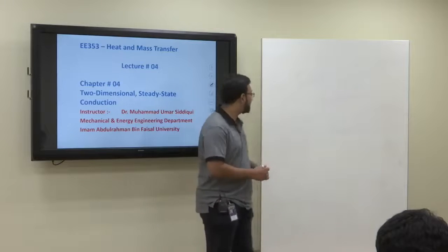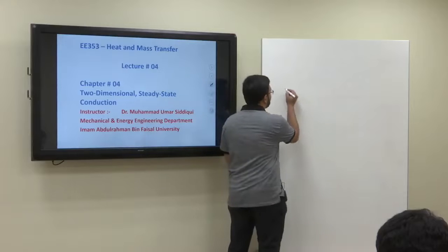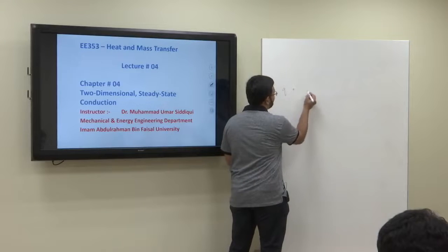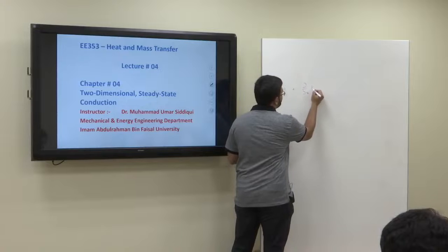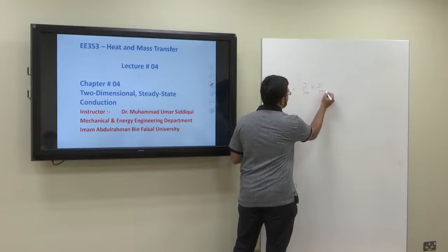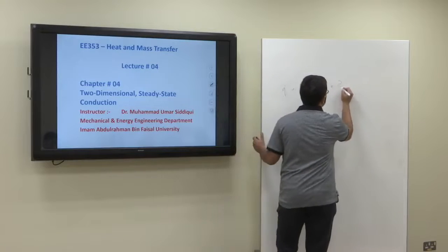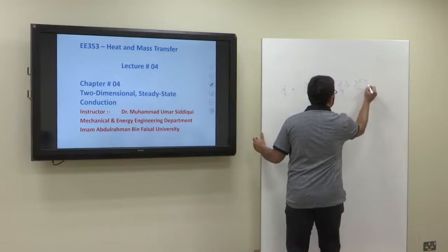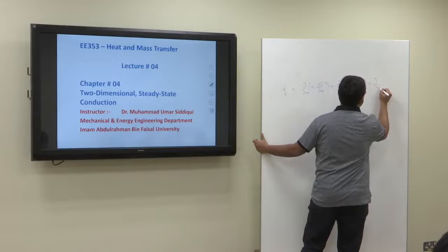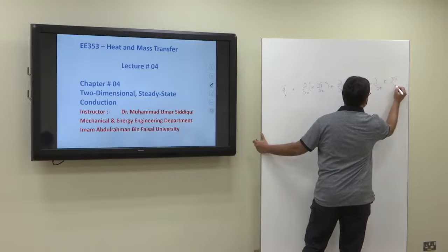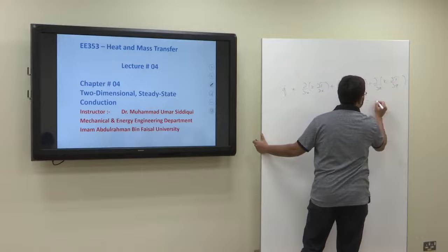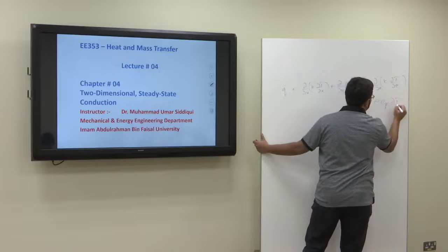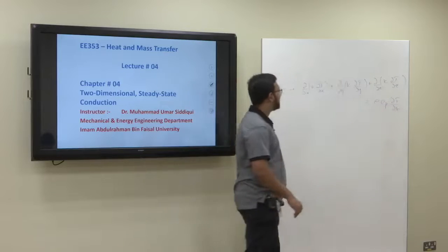Okay, you remember the heat conduction equation. Heat conduction equation was what? Q dot plus ∂/∂x (K ∂T/∂x), plus ∂/∂y (K ∂T/∂y), plus ∂/∂z (K ∂T/∂z), is equal to rho Cp ∂T/∂t, right?